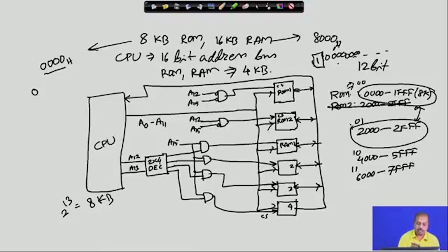If I write the bit numbers 15, 14, 13, 12, the last 4 bits of this address space. Now, for the RAM selection, bit 15 is always 0. Bits up to bit number 12 are utilized in the ROM selection. If these two bits are 0 0, the remaining bits A0 to A12 can vary from all 0 to all 1.